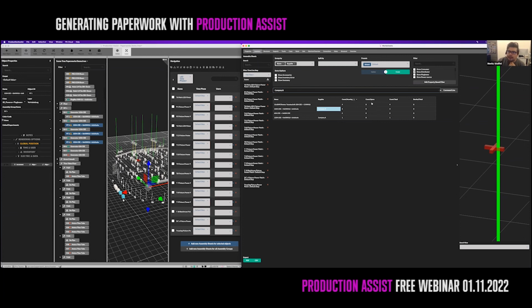You can also define a spare count. So how many spares do you want to order from company A or company B? For this, I just go into the spare and tell it I want to have 2 spare of this. And then you see the total count goes up. Then I have 3 of this, 2 spare and 5 total. And I can type in how many I have booked, so I can type in 5 with this. When I enable the option to show inventory errors, it shows me all the ones where the total booked count is not matching the actual total count.